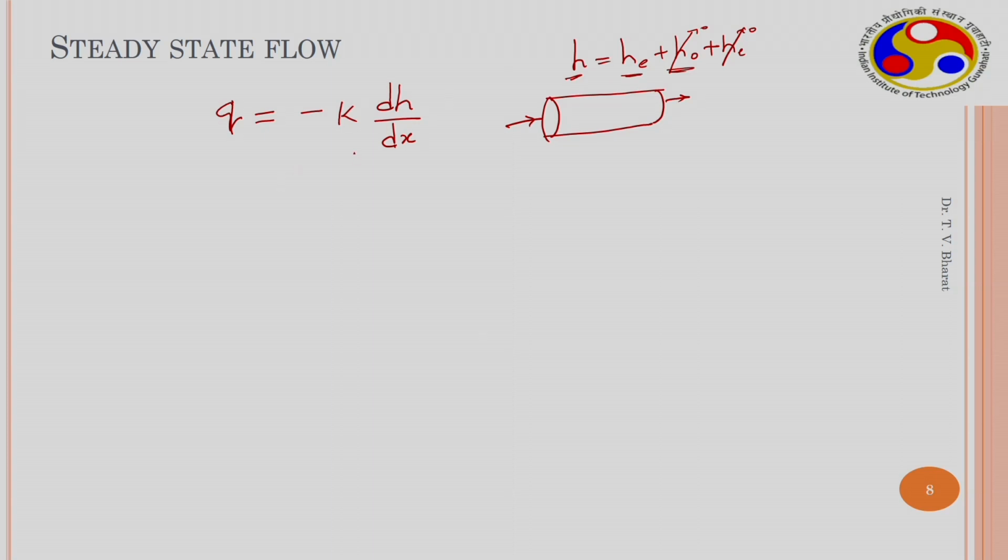So therefore here the K is a functional form. So now K needs to be substituted some value. So what K values can we substitute? We can use a simple expression for K, which is simply A plus BH. So the K varies with head in this particular manner. As the head increases, K decreases.